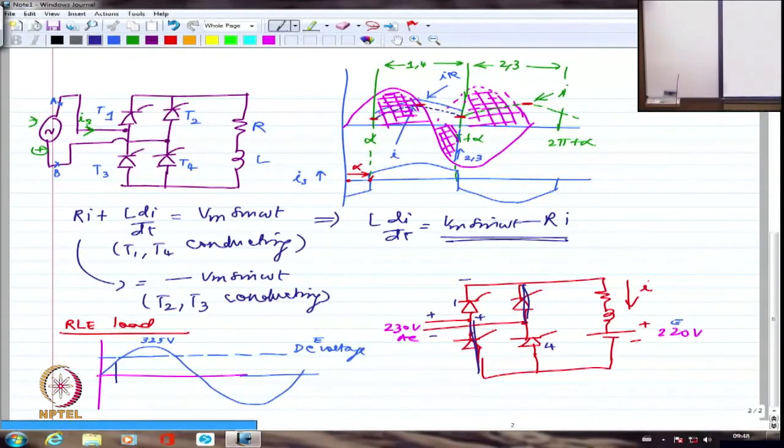So obviously device number 1 is forward biased, irrespective of whatever voltage is there in the inductance. It doesn't care. Same way, if I consider device number 4, this is minus, because this minus is directly connected here, and this is plus, and this is a short circuit, so this will automatically be plus. So no matter what, this device is forward biased, irrespective of whatever happens here.